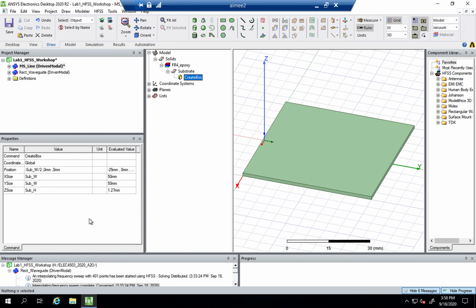line. Since we're operating at fairly low frequencies, the thickness is going to be small anyway, so we can just choose a 2D surface instead of an object. And since we haven't done that yet, I'm going to use a surface instead of an object for the line in this case. But just so you know, you can also choose a trace with a certain thickness, which is of course more realistic in a real life application.